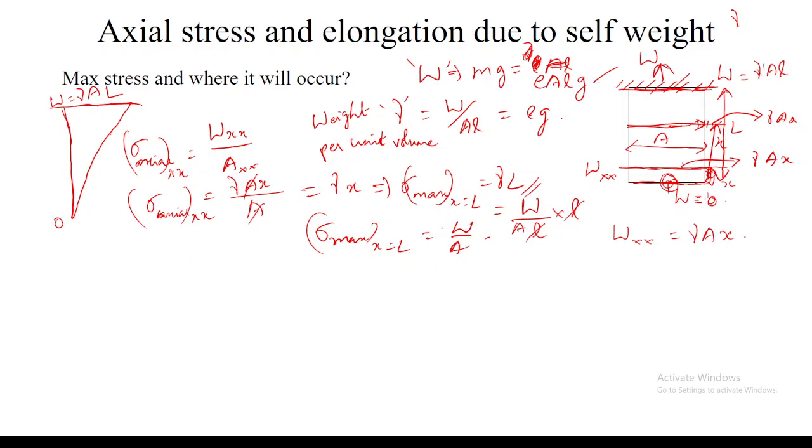Okay, in terms of load I have written the self weight. Now I am proceeding to the deflection or the deformation due to the self weight. So deflection delta L is equal to the integral of Pxx dx divided by Axx into Exx. Here it is made of the same material, so I am taking it as E, and I am integrating it from 0 to L.